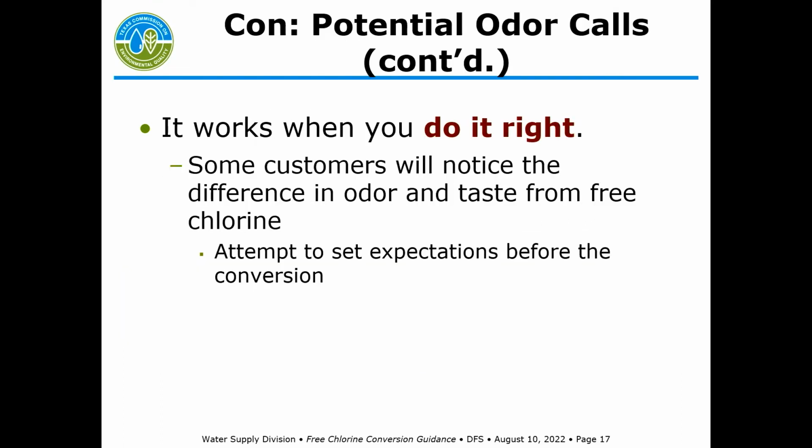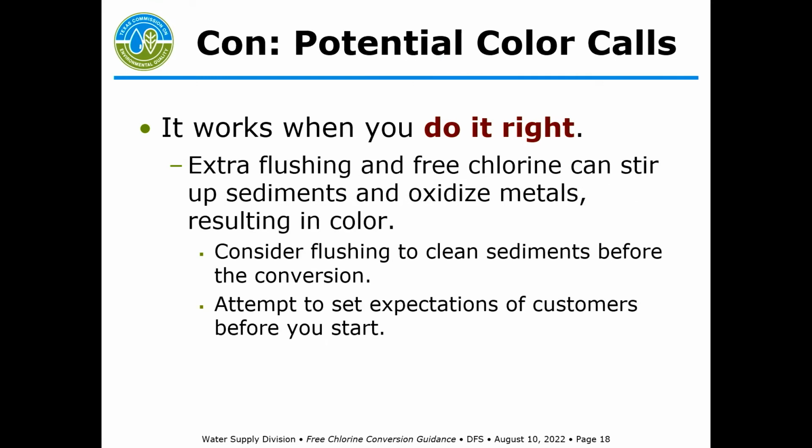So again, it's just emphasizing that doing this quickly and efficiently is going to help you on just the complaint side. Other odor call issues: just having free chlorine in the system, that residual tastes different than your normal chloramine residual, and some of the customers may complain. So it's always a good idea to try to set their expectations ahead of time. Yes, the water is going to taste different, but it's perfectly safe. It's not going to burn your skin or anything like that. That is a good idea.